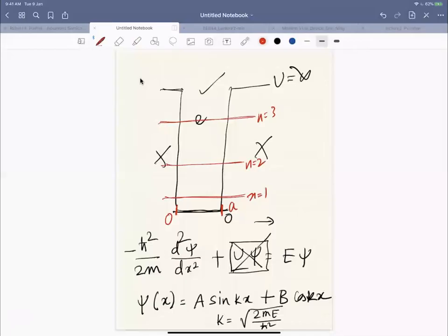So if I come back to the density of states, here the things are discretized. If you take the density of states per electron volt per centimeter cube, you see the density of states decreases. For a free particle, the density of states is infinite, right? So the electrons can be in n number of energies because it can be at any energy. But for a confined particle, the number of energy states is discretized, the number of energy states is less, right?